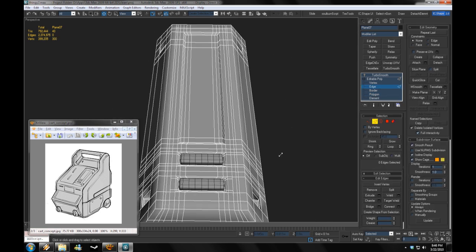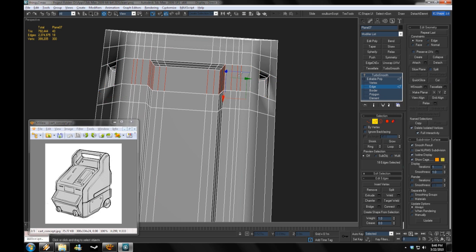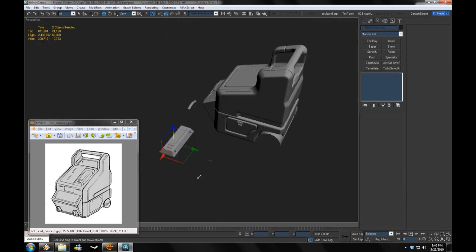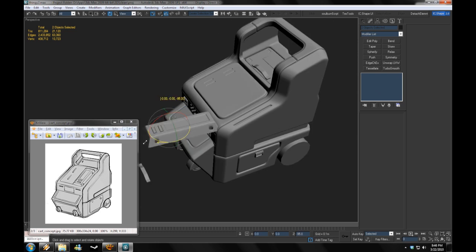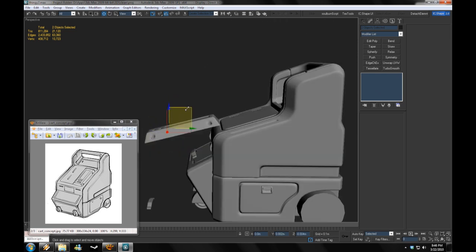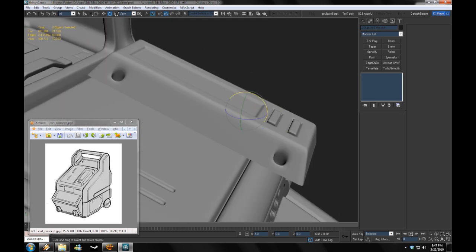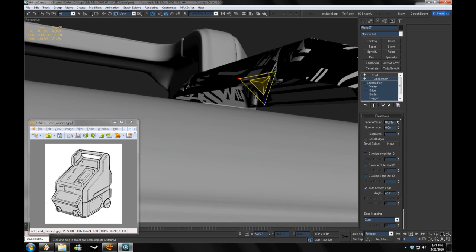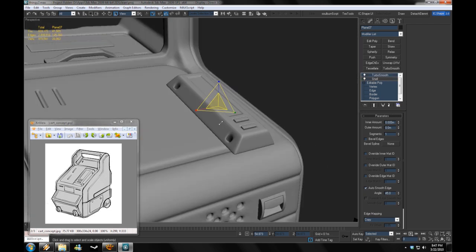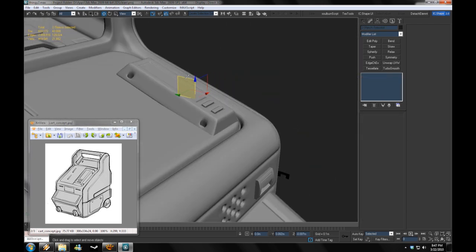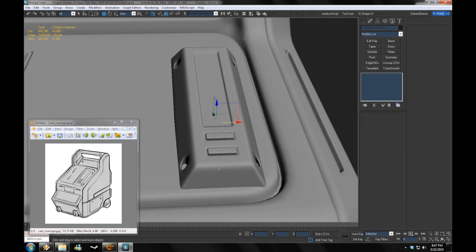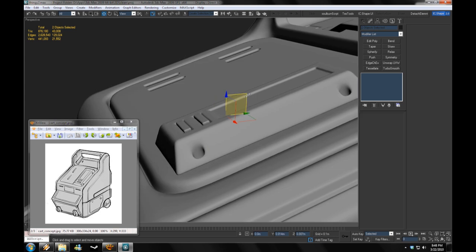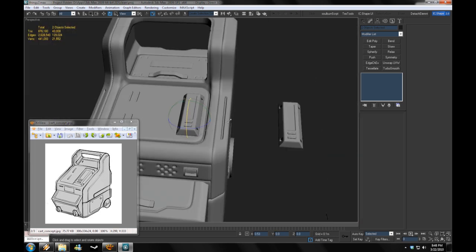So now I'm going to manually add in everything, all the control edges, and try and make everything mesh well with those little screws. There are a lot of N-gons on this, but you can't really help that a lot. It looked fine anyway, so whatever. N-gons aren't really a big problem. A lot of people like to make them out as being the devil, but I don't find them a problem at all unless you're making them on curved faces, and even then it's not really that big of a deal because all it's going to do is going to make them down into tris anyway.